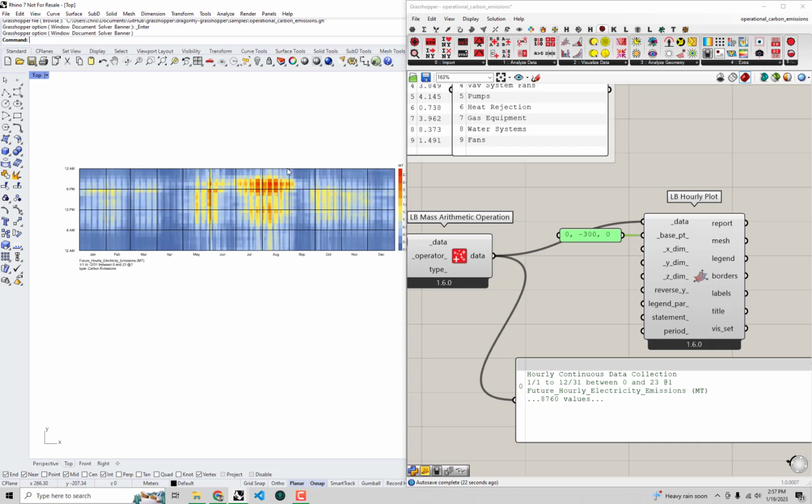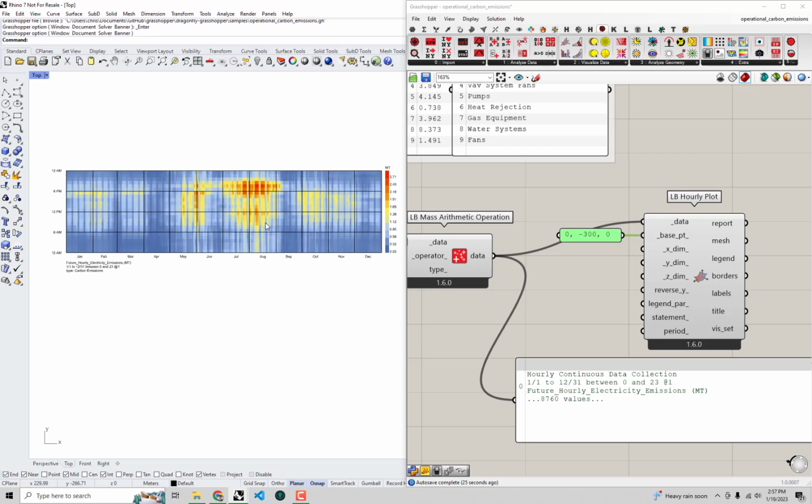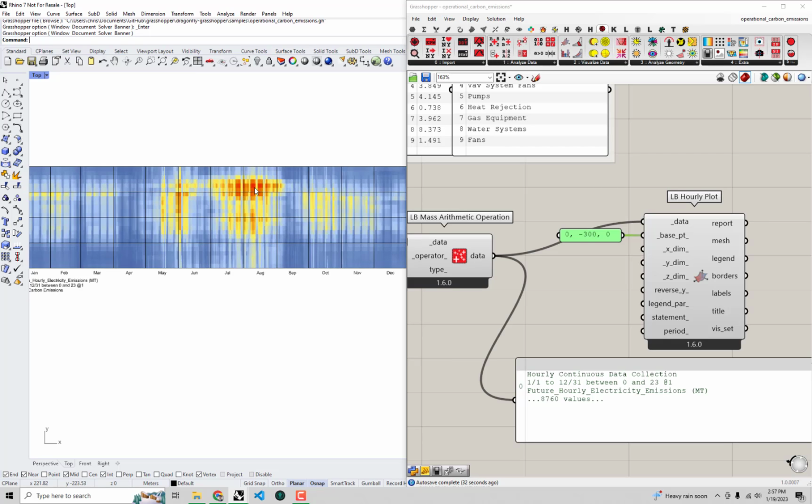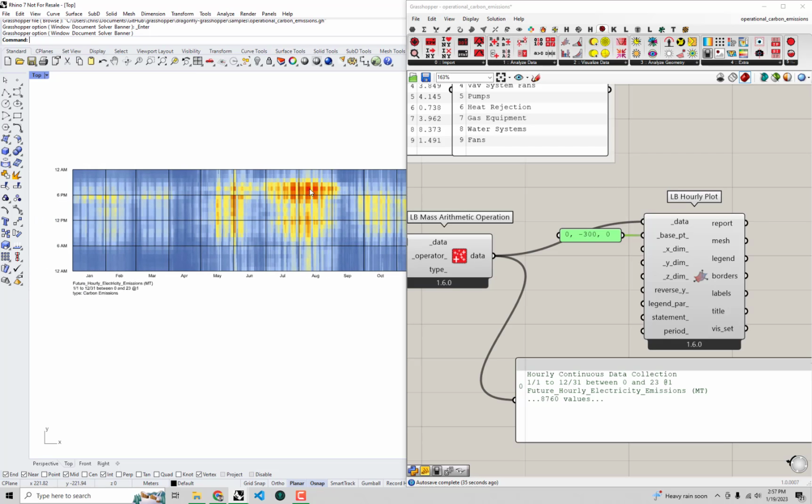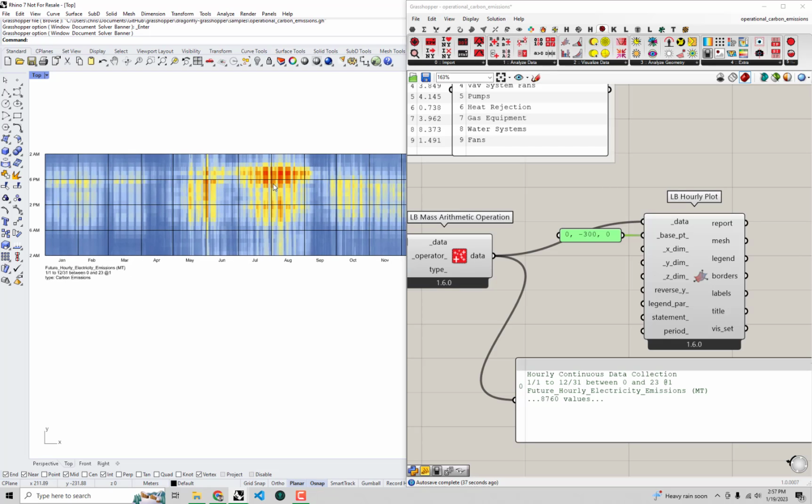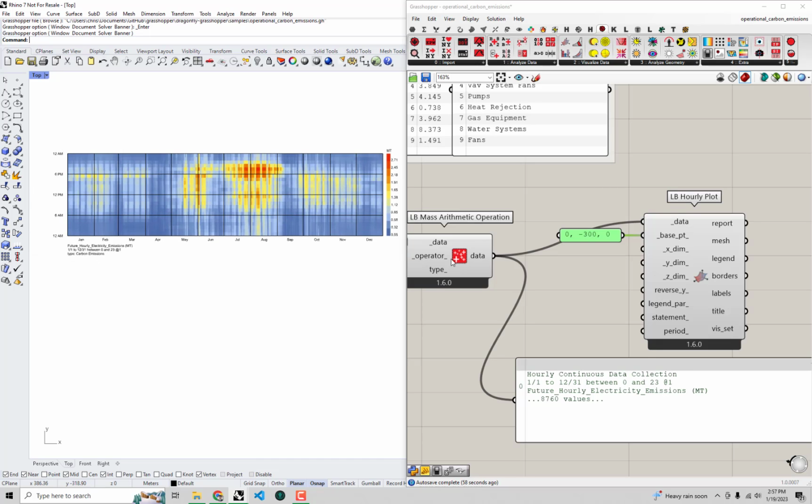And very interesting, right? You see that that maximum carbon intensity is probably not happening when there's the peak electric demand from our district, right? Instead, it's happening at around 8 p.m., probably more 8 p.m., in the middle of July and August, and we can kind of understand, right? That's the time of peak electric demand for most locations, in the middle of the summer, soon after sunset, when all the air conditioning's on, but everybody's cooking and got all their appliances on at home. So that's basically when all the gas turbines are being switched on, and that's why the carbon intensity of the grid is going up so much.